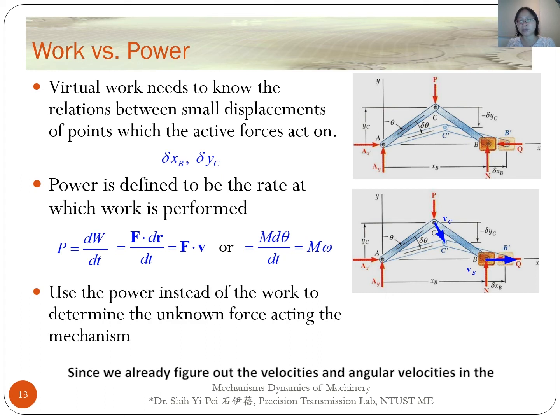Since we already figured out the velocities and the angular velocities in the mechanism through the velocity analysis, it is convenient to use power instead of work to compute the unknown external force acting on the mechanism.